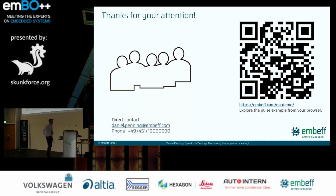Yeah, so we have some very simple registration mechanism. So with each device, we ship some little sample package, and that's a sample package for some drivers, but most importantly, a little piece of our software. And it basically talks to our test system with, for example, UART, and receives the commands which functions to call. And basically, you need to go beforehand, register all the functions you want to call, and then you can do that at runtime.